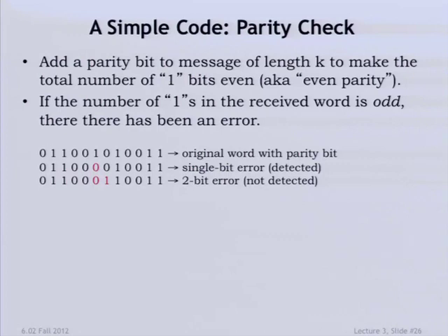Yeah. So then if you flip a second one, you'll either still have an odd number or you'll have, okay, good. So an easy way to see this is to flip one of the message bits and flip the parity bit, for instance. No, that doesn't do it, does it? Because then you've changed 2 zeros to a 1 or 2 ones to a 0, and your parity is wrong then.